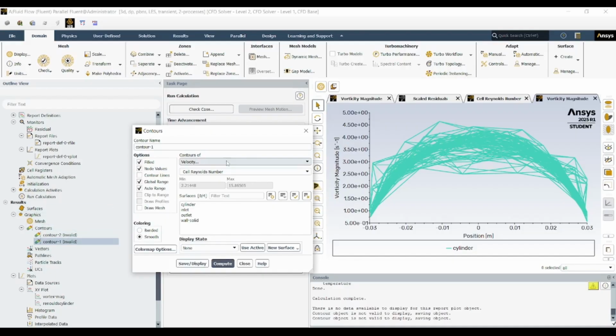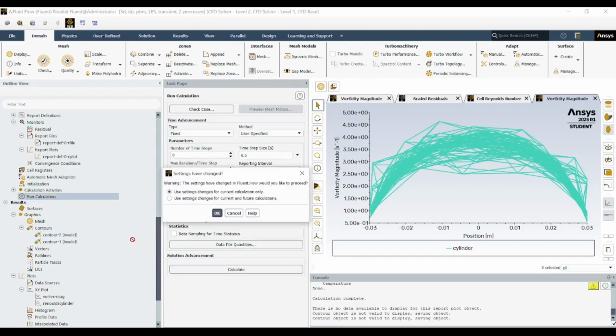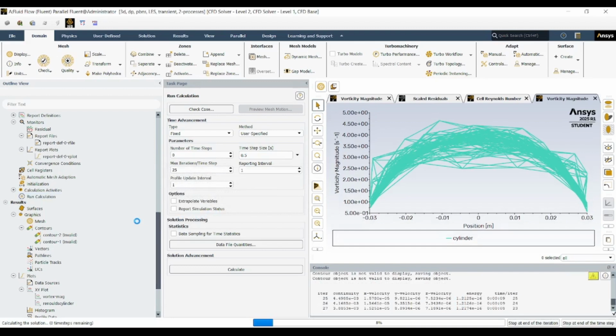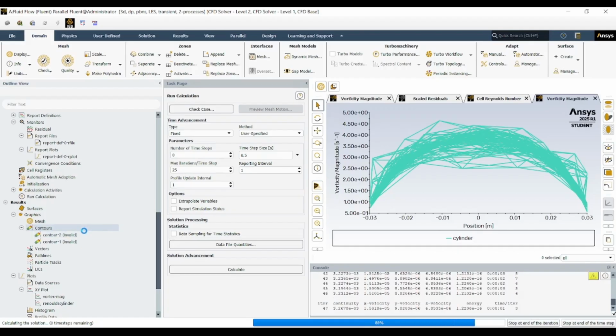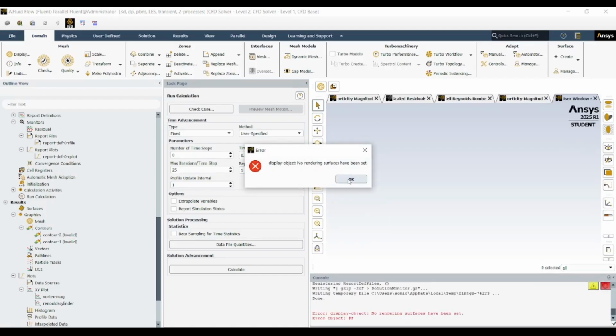In the same way, when displaying contour plots or vector fields, label the color bar with units, e.g., velocity magnitude, meters per second, or pressure, Pascal, and use a consistent color scale across all visuals to maintain uniformity. Proper labeling not only improves the presentation, but also ensures that your analysis communicates results clearly to viewers and readers.